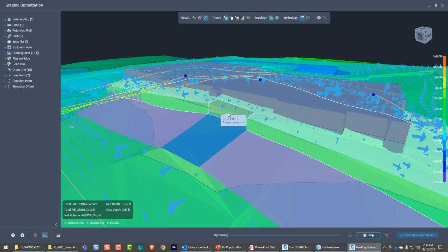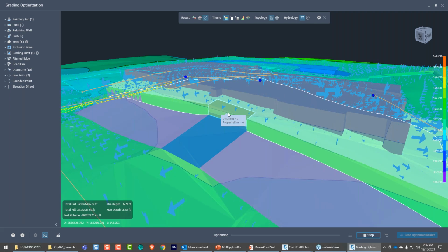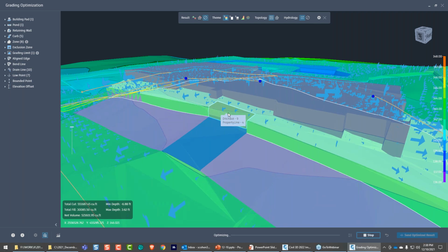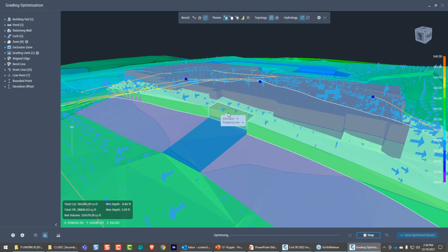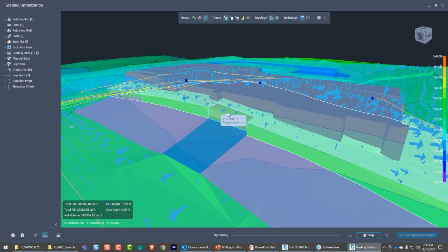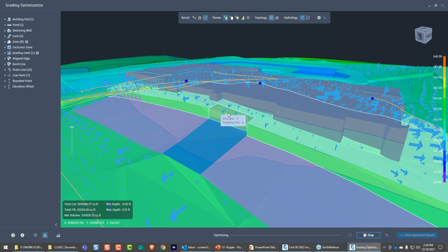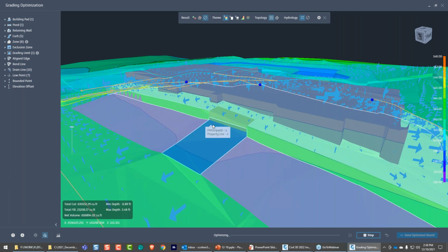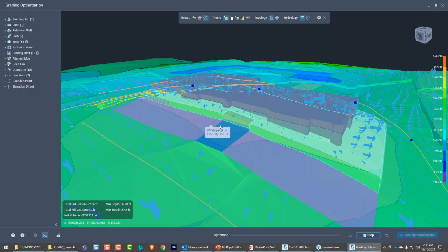If I want to do feature lines, I have a block that has all the linear objects for the ramp, the 88 ramp, and I can just set the elevations based upon my existing or my proposed surface at this location here. It doesn't bother me that I'm not getting a ramp. That's the kind of thing you have to realize: as long as it gets you 80% there, you're fine. I know I've said that 1,000 times. Anyway, that's what this is doing.